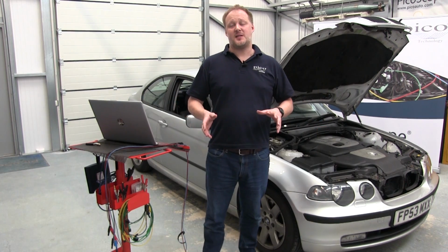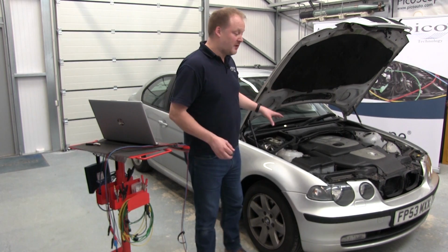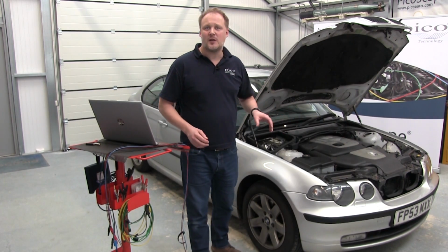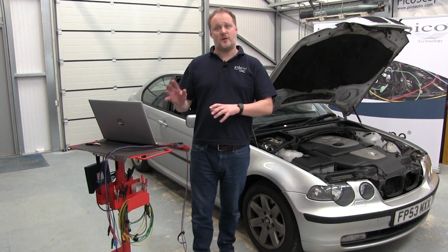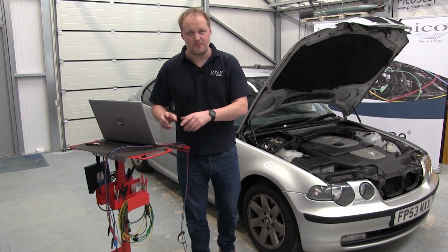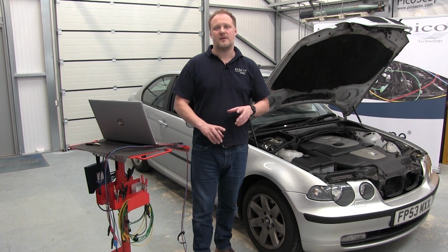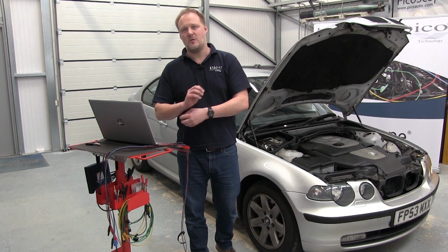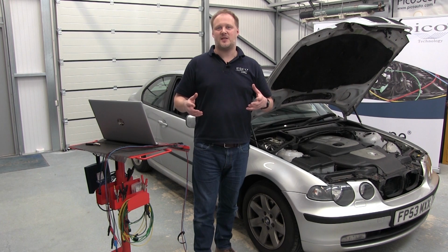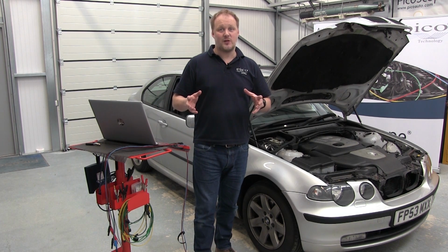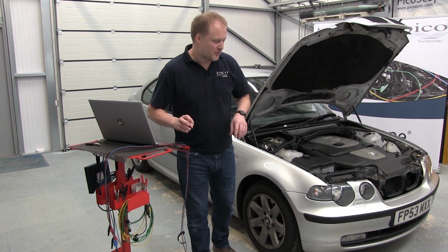In this part of the presentation, we're going to look at the common faults that you might find on a CAN bus network and how they affect the waveforms that you see on your screen. For example, there might be shorts to battery positive, battery negative, short from CAN high to CAN low, open termination resistors or open circuits generally, all those types of things.